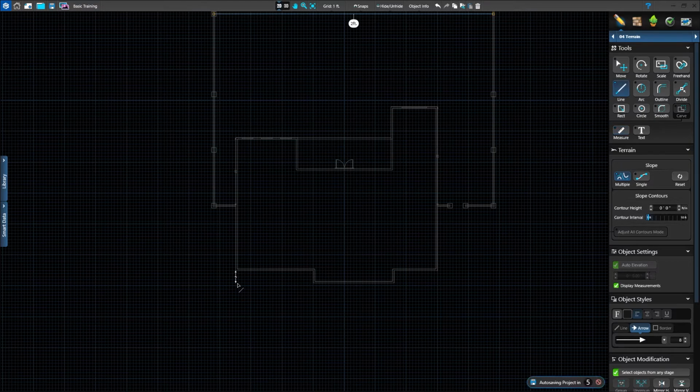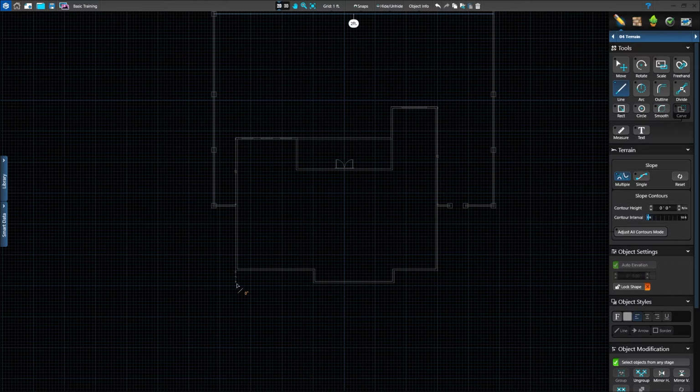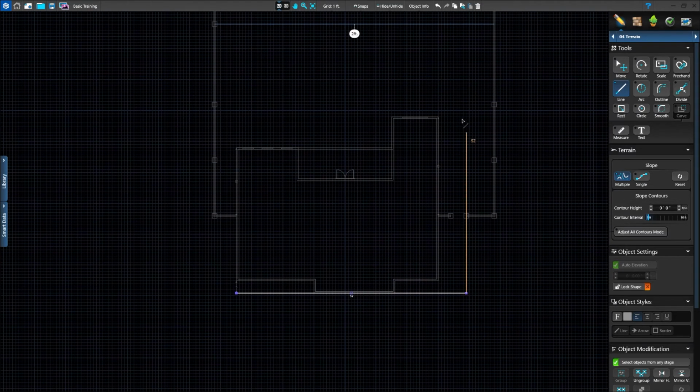Press A to activate the Line tool and left-click at the end of the 4-foot measure guide to start the line. Then move your mouse to the right 74 feet and left-click. This aligns us with the gate to the backyard. Now draw up 80 feet and left-click.